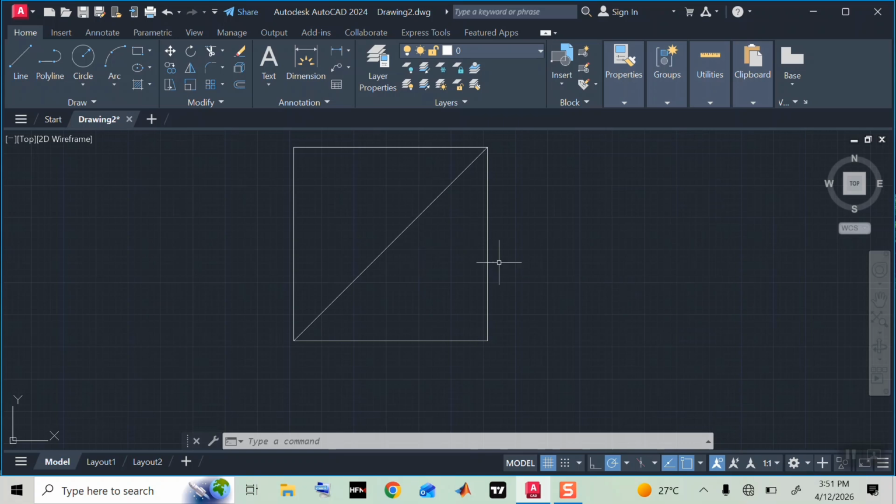After that, we can now select our line, enter, then here we right click up to, you can see this blue line here. Now this one is at the center of that diagonal. We right click, then enter to complete that drawing. You see, we can also draw a line from midpoint to midpoint.